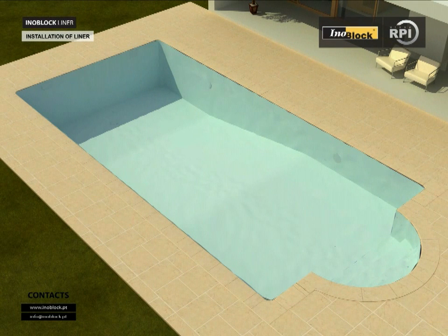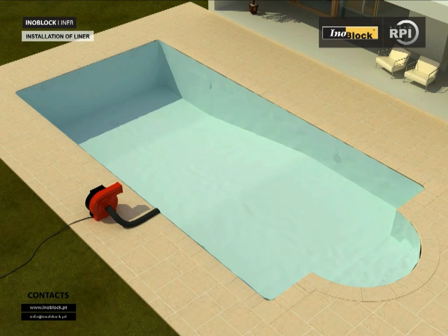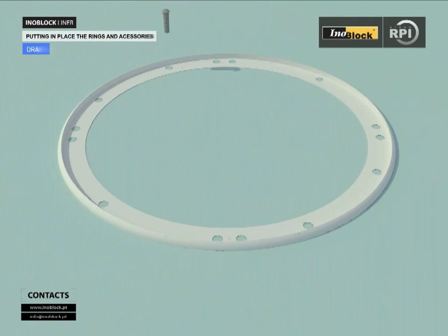Start by placing the liner into the groove which runs around the top edge of the pool. Once the liner is in position and spread out over the floor of the pool, using a vacuum to suck out the air from the space between the pool wall and the liner will help remove any wrinkles. You can now begin filling the pool with water.